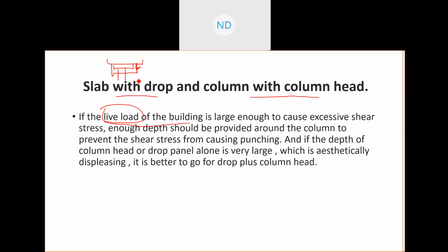Also you don't have to provide false ceiling there. Why do we provide false ceiling? To hide the beams, for a very good look of the room. But when you use flat slabs, you don't need the false ceiling, because there is no beam already. It also decreases the room heights, excluding the beams.